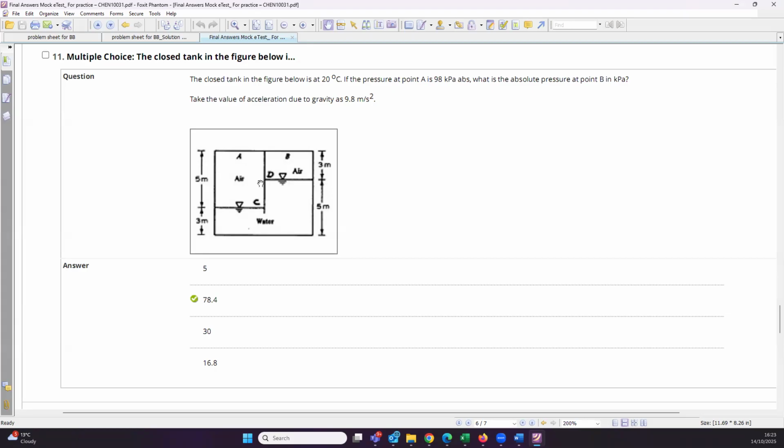So what you need to solve this question, you again find a point where you can equate pressures, and most of the time these points are where the two fluids meet. Okay, so that is again another hint that you can use when you are trying to find these points where you can equate, is where the two fluids meet. So that is, let's say, this point. So let's call this point as elevation 1. Okay, so what would be the pressure at